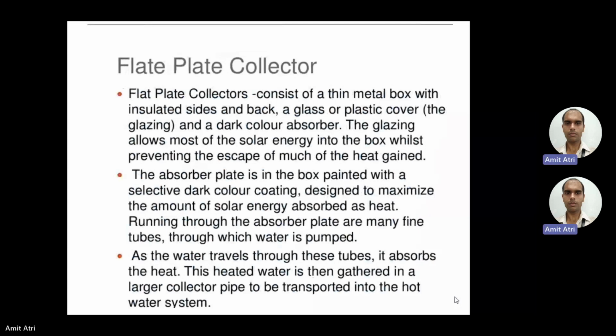Okay, so metallic flat plate absorber, tube or channels for the fluid, then transparent toughened glass sheet, protection as well. Also one more thing the glass offers, that is greenhouse effect, collection of heat. Okay, then fiberglass insulation, so that the heat should not leak to the environment. Coming back to the construction working point.